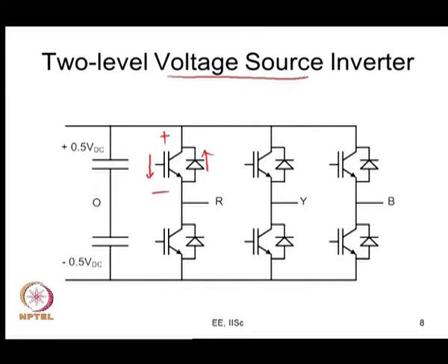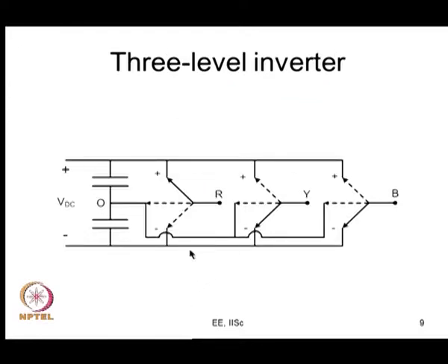If you are going to the current source inverter, you will need the complementary, the dual of this. A current source inverter would require a switch which can block voltages of 2 polarities, but maybe conduct current in only one direction. Alright. So, this is a voltage source inverter, and it is realized using a single pole double throw switch, as I have shown here. Now, we need a multi-level converter. What we do is, single pole double throw, there is a pole.